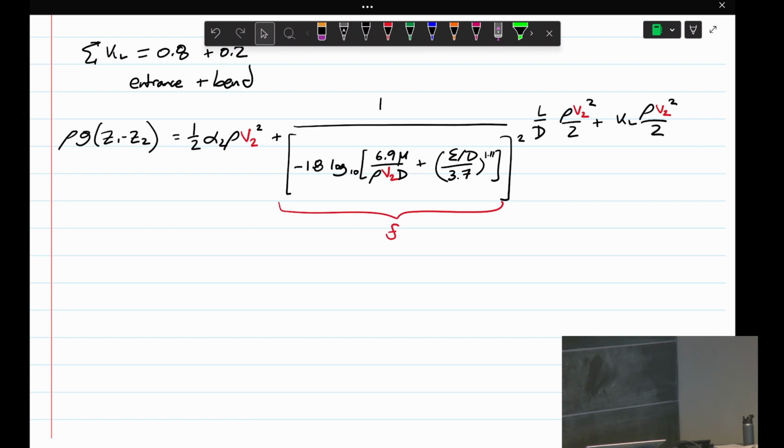So the L in our major losses there is just basically the length of tubing we have. I think it's roughly 17 inches here. So if we just measure the straight length here like this, it's roughly, sorry, this tube sucks. 17-ish, good enough. 17 inches, so that's L. For Z1 minus Z2, remember 1 is the top of the reservoir and 2 is the discharge point. So this definitely varies. If I move this, it changes that Z1 minus Z2.